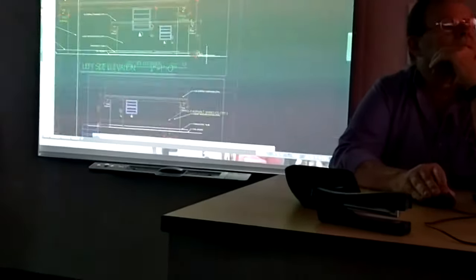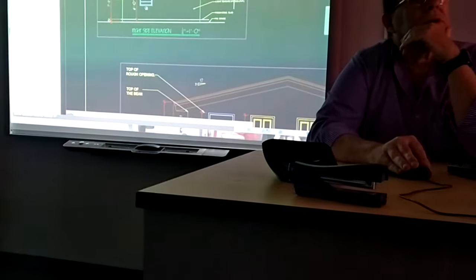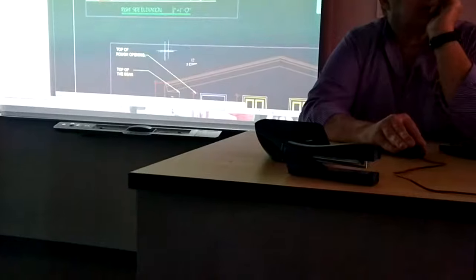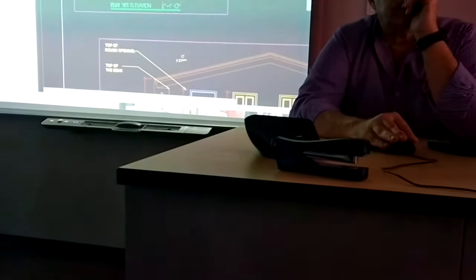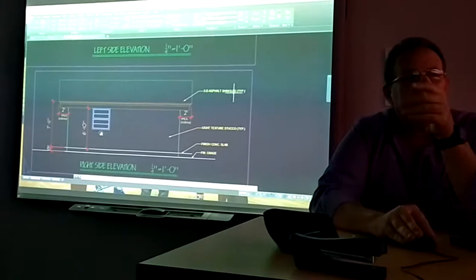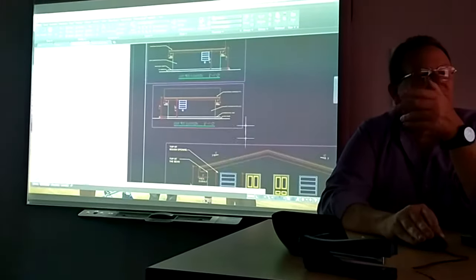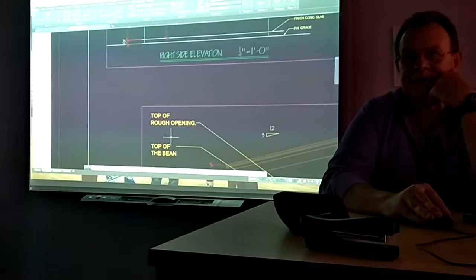Okay? And then in model space, what I'm gonna do is change this to 1/8 of an inch. Otherwise, you're not being consistent. And also, you gotta be careful too, because then your text over here is 50% smaller than the text at 1/4 of an inch. So if you need to do this smaller detail, then in model space, you make this text twice as big, so that it is compatible with this one at 1/4 of an inch. See what I'm saying?